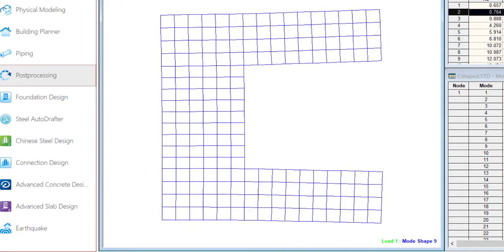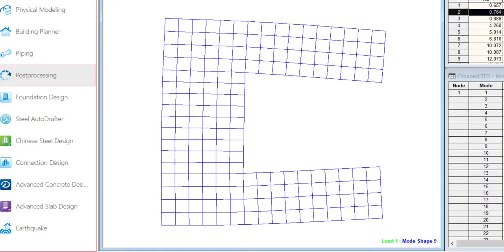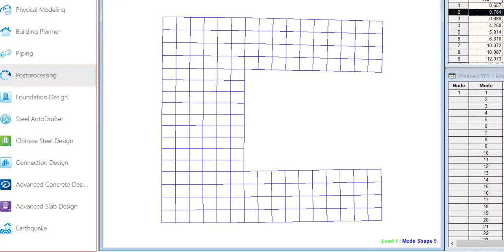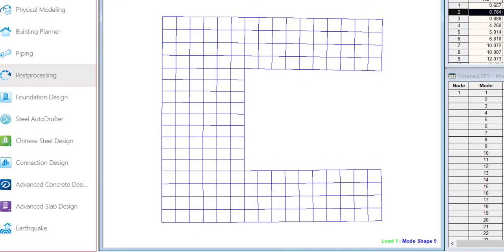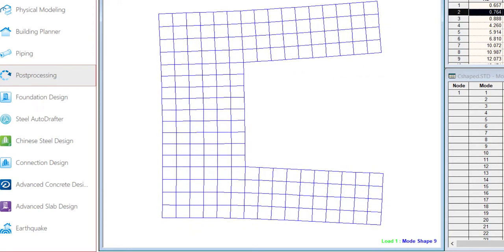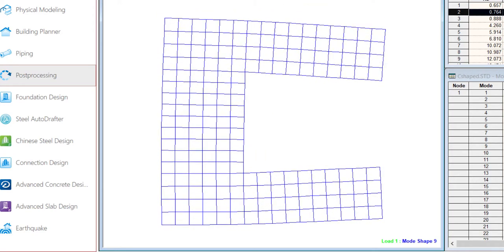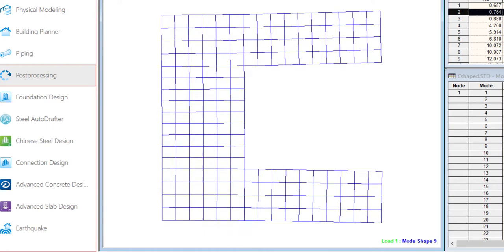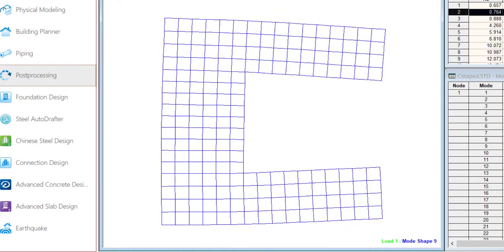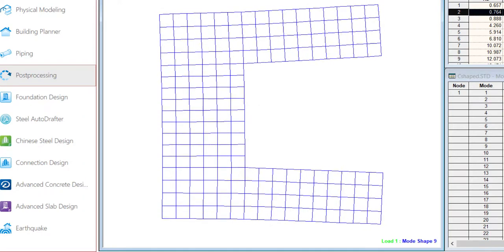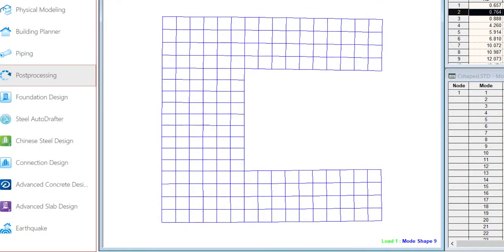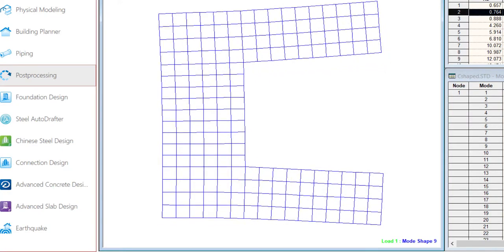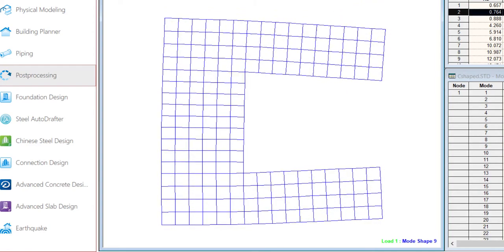But as there is no such link between these two wings, and also these kinds of floor plans are very slender, there could be a significant amount of internal deformation, and this deformation may lead to a significant amount of internal displacement. For example, at these two extreme ends of the wings, when you are assigning it as a rigid diaphragm, then after performing the dynamic analysis, the eigen solution could not capture any mode having this kind of open and close mode shapes. That's because we are treating this floor plan as rigid.